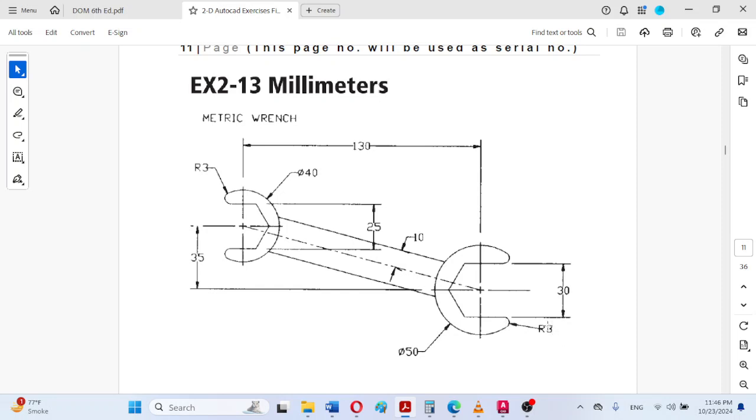So either we must change the radius of this tangent radius circle, or we can type this dimension to be 35. As for the hexagonal jaws, this tangent radius dimension is the same and correct, but this dimension is actually wrong. So this must be 35. Kindly make this correction and note it.